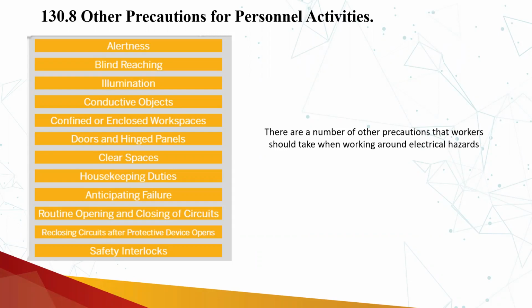Doors and hinged panels need to be secured tightly and safely, because due to the movement of those doors and hinged panels, there is a chance that a person might fall onto the live parts on which the task is being carried out. Clear spaces need to be kept clear.